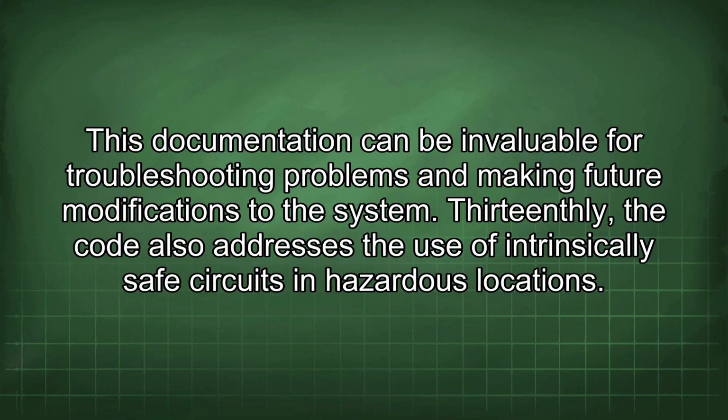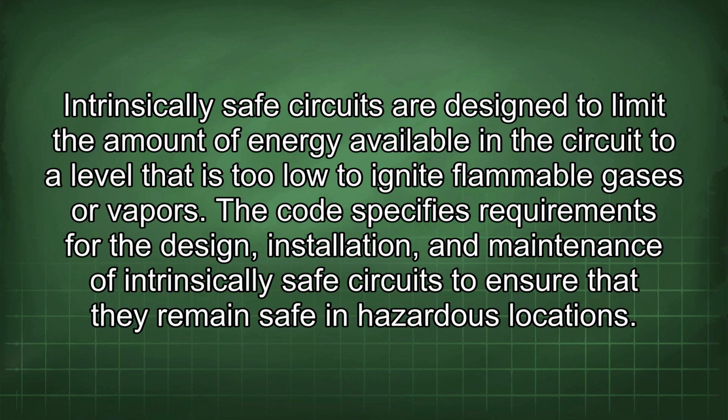13thly, the code also addresses the use of intrinsically safe circuits in hazardous locations. Intrinsically safe circuits are designed to limit the amount of energy available in the circuit to a level that is too low to ignite flammable gases or vapors. The code specifies requirements for the design, installation, and maintenance of intrinsically safe circuits to ensure that they remain safe